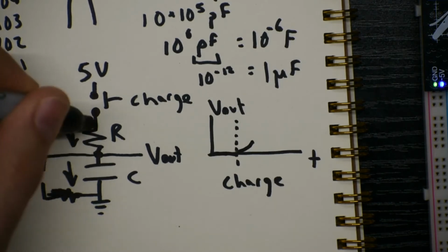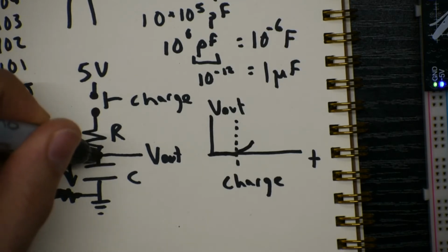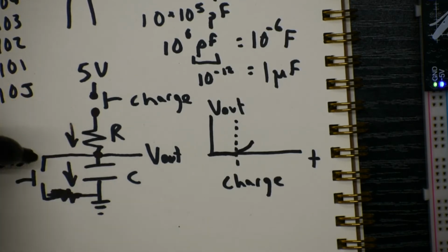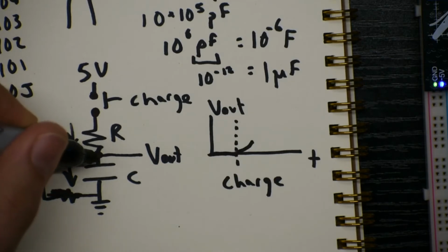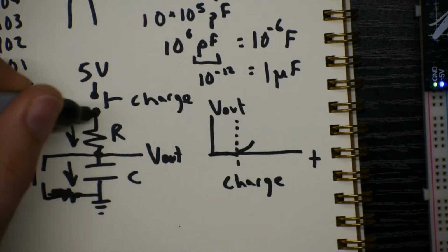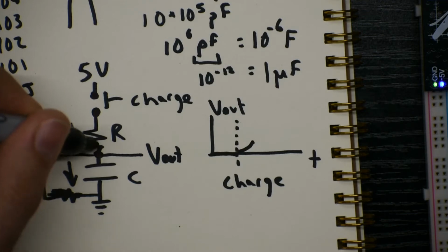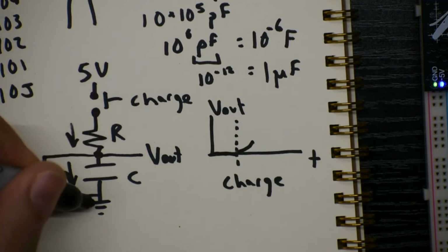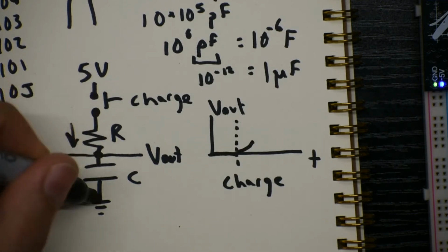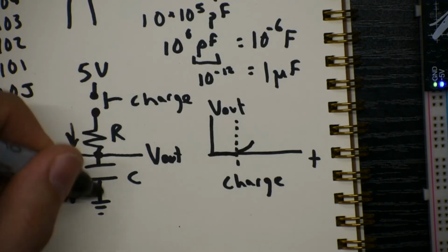So initially, we've got V equals IR. Now, let's say we wait a little bit of time. Now this voltage has been integrating that current. So this voltage is now, I don't know, 0.1 volts. So now there's only 4.9 volts across the resistor. So the current decreases because we've lost some of the voltage, the total voltage across the capacitor.